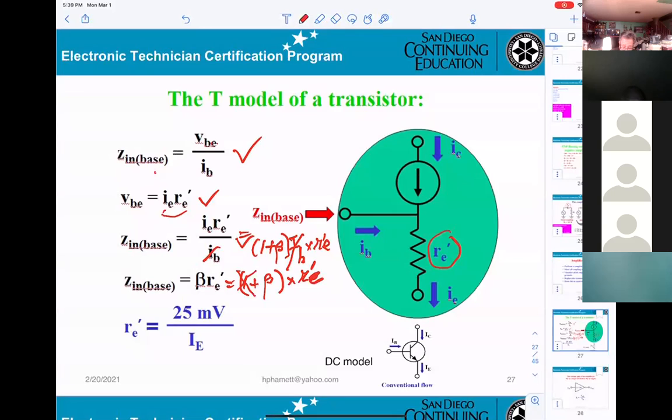Right now, if you're looking into that module, I expect you are able to understand that if you want to calculate the resistance at the base, you can use beta times R prime E. I guess what I'm asking is for a formula. I don't know if there is one, a formula for beta only, AC beta. No, I said AC beta or DC beta, depending.